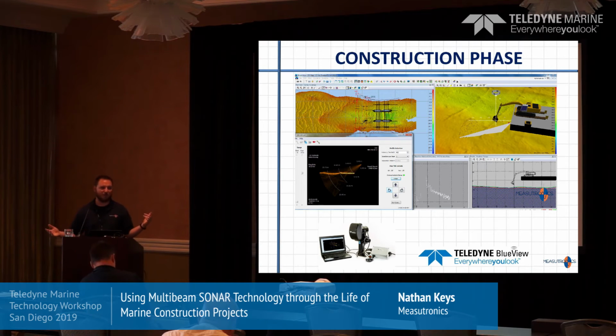And so GPS doesn't really work under the bridge. So we were using a total station, and we used a Teledyne gyro compass to do heading, and it was a pretty cool project. Again, they're making sure they place a bunch of rock, and then they scan it with the sonar, and the sonar tells them, okay, yes, that's enough rock, it's too much rock, or not enough.